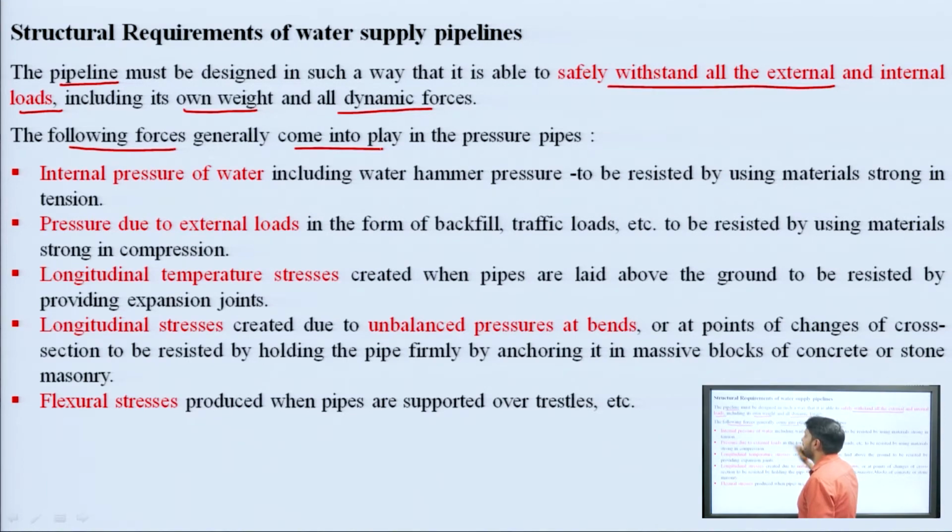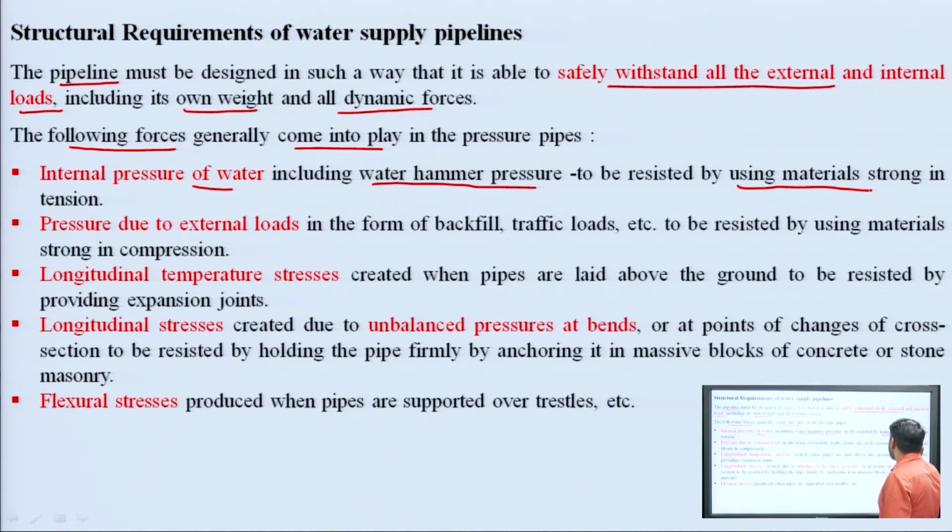come into play. First one is the internal pressure of water, and this internal pressure of water includes water hammer pressure. This water hammer pressure will be resisted by the pipe material itself, and the pipe material which is used should be strong in tension.